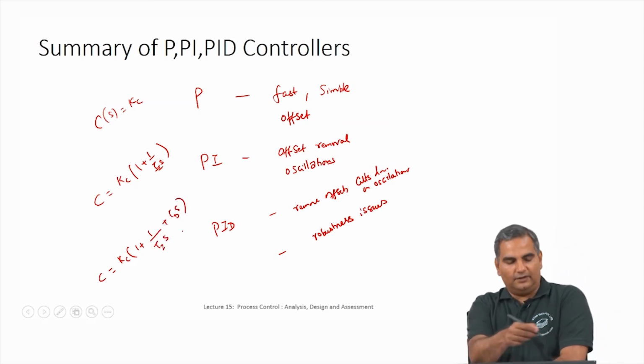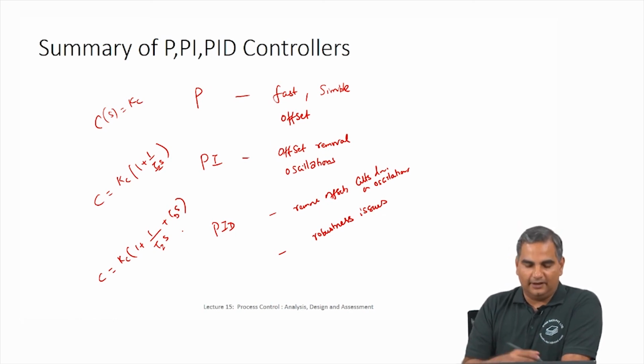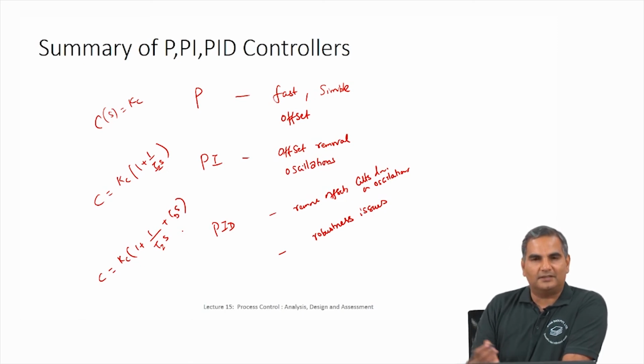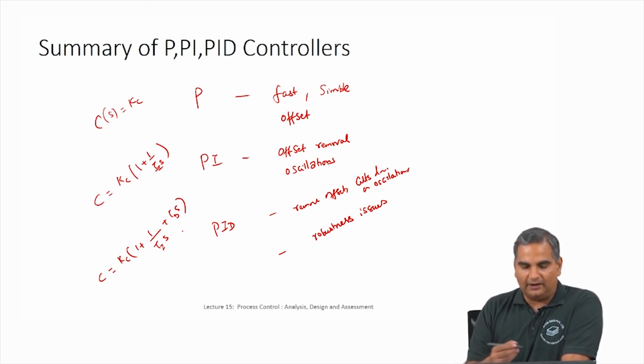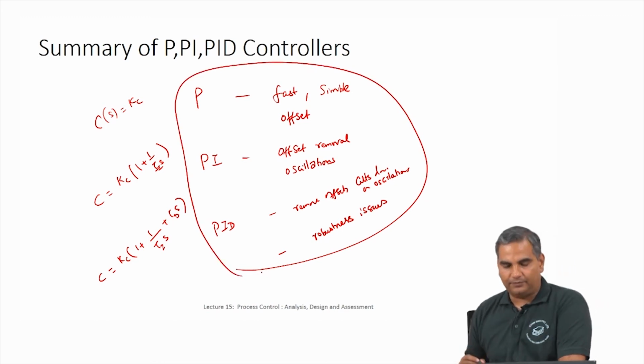Okay. So all of these are transfer function forms. You just put them into those equations and then you do your basic numerator by denominator polynomial, partial fractions, inversion. You can analyze all kinds of controllers, and this is an important set of ideas when someone talks about these three types of controllers.